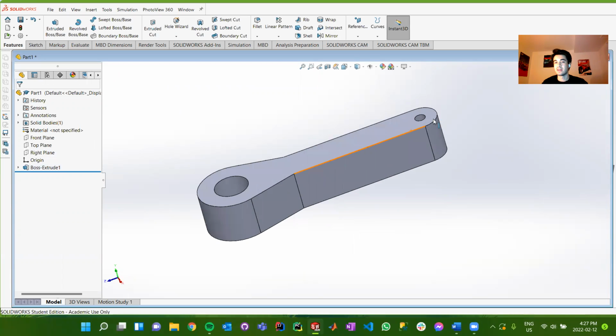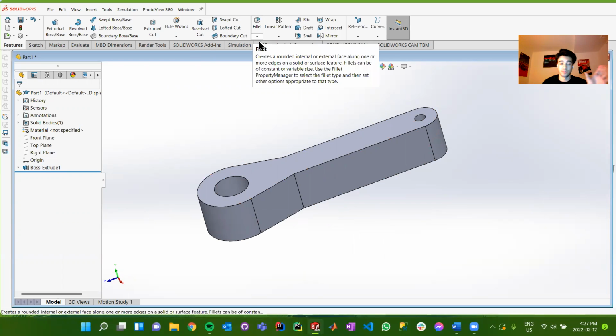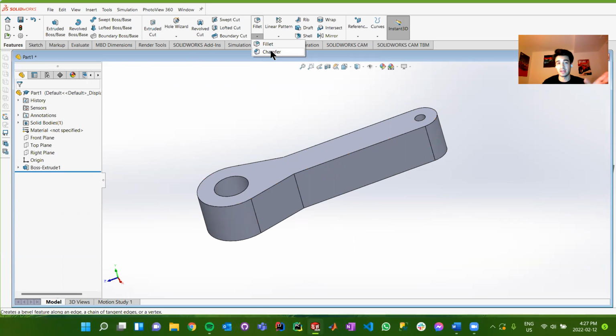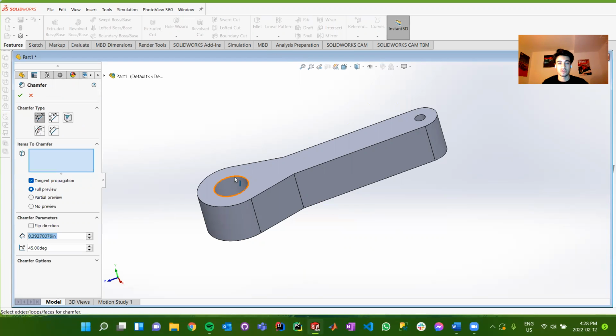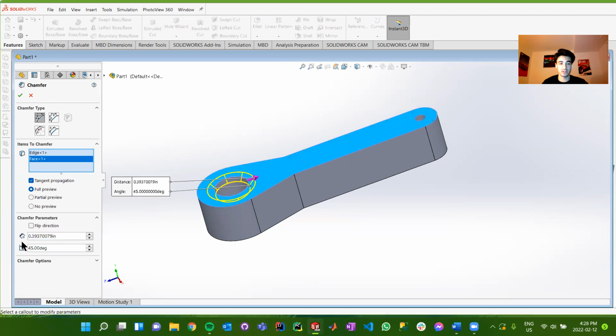As you can imagine, on this end, the chassis will be connected to our arm, and this end will house the propeller. Awesome. Now from there, what we can do is make this look a little nicer and get rid of all these stress concentrations in the middle by adding a set of chamfers. So I'm going to chamfer this edge, this top edge as well. You'll notice it's not previewing anything because this chamfer is actually too large for the object. Let's reduce it to 0.25 inches.